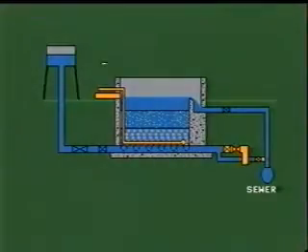The graphic illustrates the process of backwashing. Compressed air is made to pass through the filter beds from bottom upwards. Thereafter, water enters under pressure from the bottom upwards and cleans the filter beds.